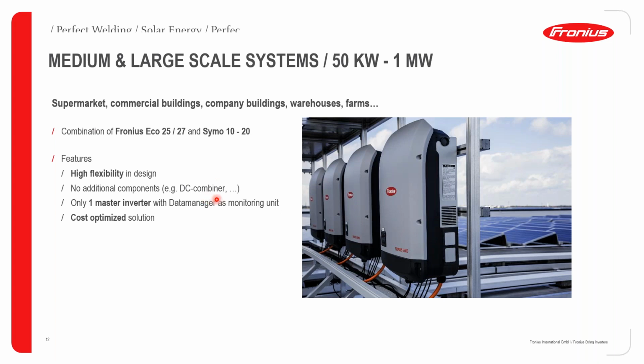So you don't need DC combiners. You don't need additional external SPDs on the DC side. Also, what's to note is that one master inverter with a data manager can control multiple inverters. For example, in this picture over here, we have 4 inverters, but only one of them has a data manager. So the other 3 inverters receive all the instructions from the master. With this sort of topology, it's a very cost-optimized solution. So you can really save costs on DC cabling, AC cabling, combiner boxes, surge protection, etc.